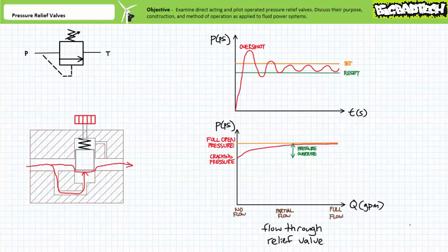In this case, our pressure relief valve has a pressure override of 100 psi. Cracking pressure is something that must be anticipated in a system and accounted for. If a system did truly need to operate at full flow capacity up to 800 psi, the pressure relief valve would have to be adjusted up to 900 psi to account for this valve's early cracking pressure and 100 psi pressure override region. This newer, higher pressure limit may, however, necessitate more robust components, fittings, and conductors. Note, preset, non-adjustable pressure relief valves exist without the adjustable knob. It is incumbent upon any technician employing these types of pressure relief valves to determine if the specified fixed pressure is the cracking pressure or the full open pressure.